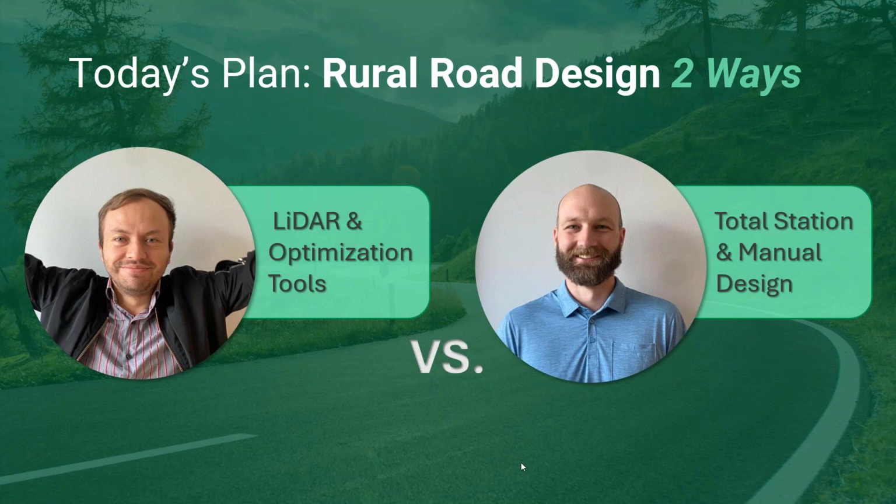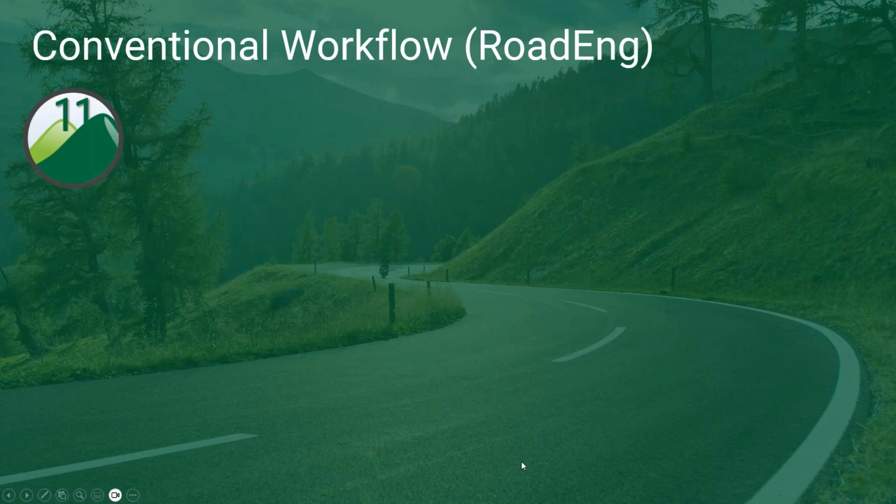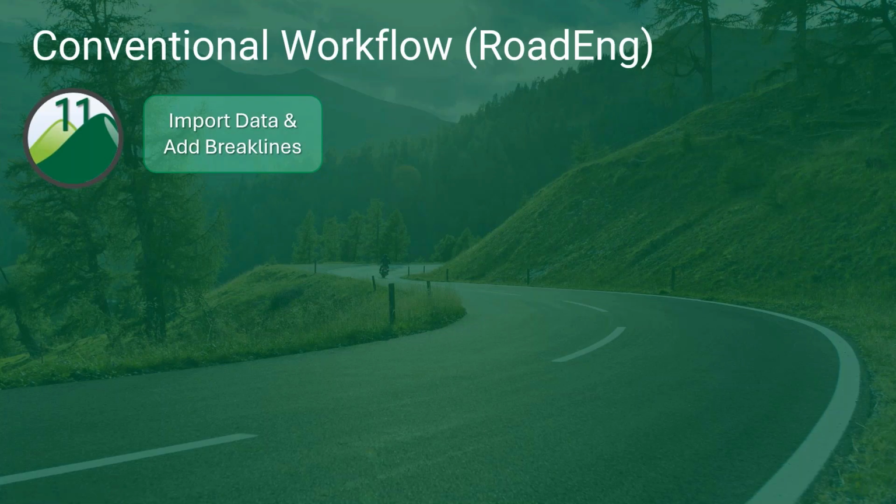So a quick look at his workflow, again, quite similar, the conventional workflow in RoadEng. He's going to import his data. One of the big notes with conventional data, whether that is RTK, whether that's total station, is the addition of break lines. You can add break lines in automatically at the time of import through something called an IOP, and Matt will talk a little bit about that. But break lines add a lot of importance to a model, ensuring that it is correct visually. So we'll talk a little bit about that.